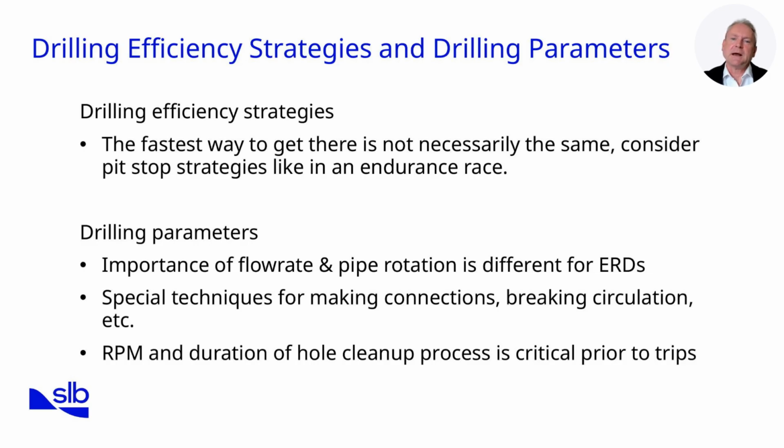Efficiency in ERD is less about speed and more about endurance, similar to an endurance race. The fastest route isn't always the most successful. Instead, we need strategies that balance progress with maintaining wellbore stability and equipment performance. Think of pit stop strategies. Sometimes pausing for hole cleaning is faster overall than pushing too hard and risking instability.